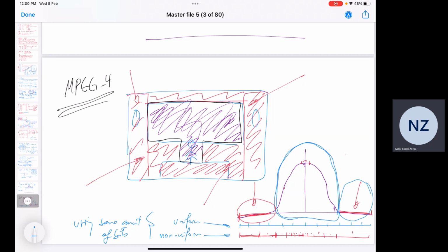So here, this standard is smart because it divided the image into important and non-important. That's the uniform. This is exactly the non-uniform. Okay, because it divided. If it has not divided the image, this is uniform. It will deal with the whole image as one single entity, everything the same. But this standard says, no, not the same. This part is more important than this part. If something is more important than another, it is giving it more priority to change than the other. This is why the non-uniform is better. This standard is the best example of non-uniform quantization. Clear? Sure now? Clear to all?